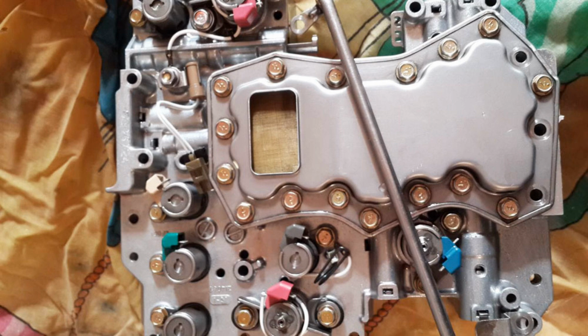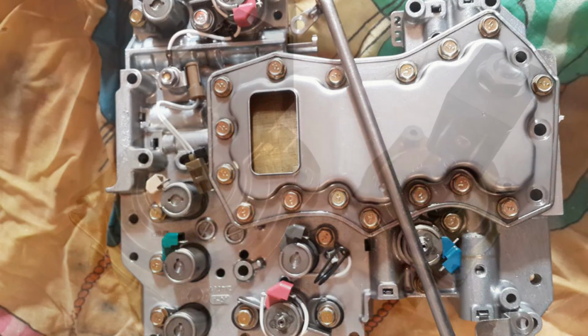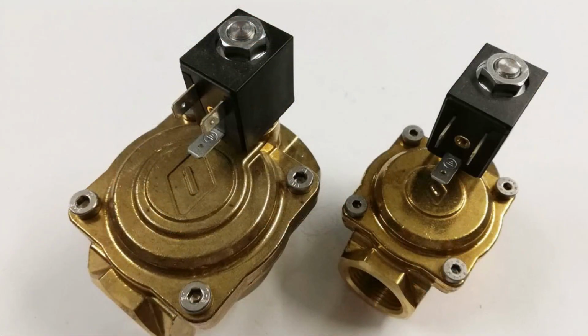If cars have an automatic transmission for gear shifting, in this case, the device functions due to commands received from the ECU, i.e., electronic control unit, which makes the solenoid an integral element of the car design. ECU continuously sends electric impulses with a certain required frequency. The solenoid monitors the pressure of lubricant on specific defined clutch links, performing quick shifting of speed or removes blockage from the hydraulic transformers.